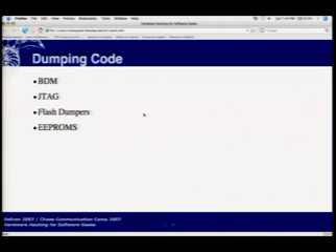The pins, there are named pins that have certain functions. However, the headers are highly variable. I've got 2 devices here, both of which have JTAG headers. One of them has 10 pins, one of them has 14. The connections are different, and it's been largely trial and error trying to get JTAG connections into these devices.